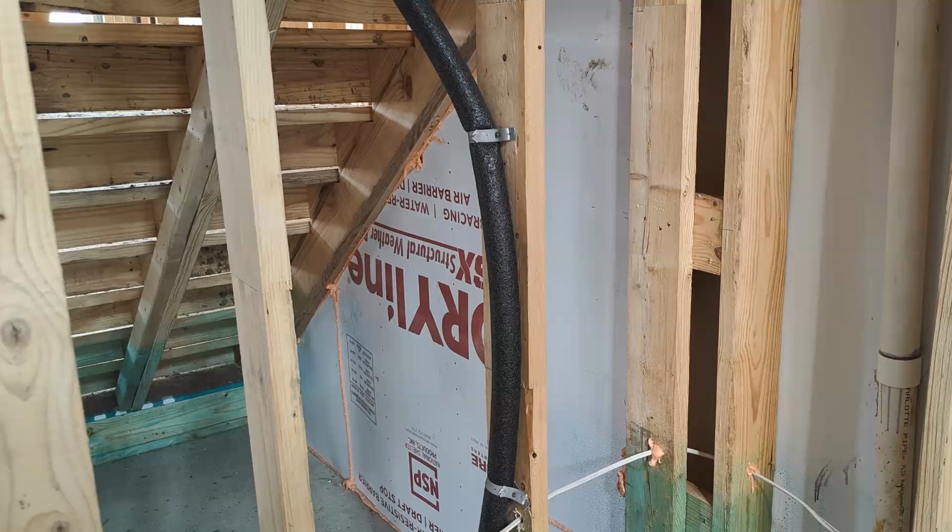We always explain it to builders that way, and they start to understand that if this structure was not here, you would already have an air barrier like sheetrock. Once you've removed that or did not install it because of the way it's being framed, you still have to have an interior air barrier. Netting is not included in that. Netting is not an air barrier. Netting is only to hold insulation in place.